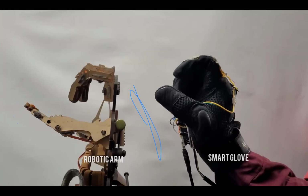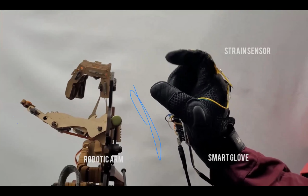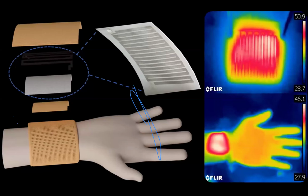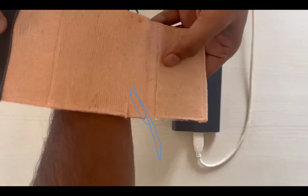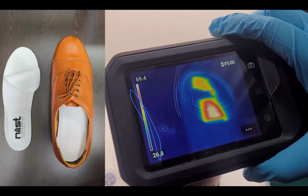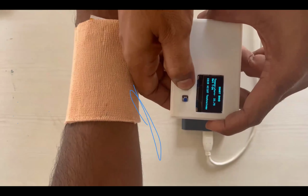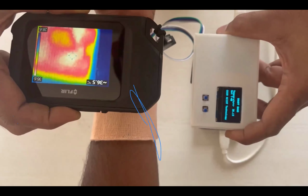The same ink is also used to develop a printed piezoresistive strain sensor, which transduces hand gestures to a robotic arm. We have also developed printed silver and carbon ink-based resistive heaters by replacing conventional coil heaters for various flexible and intelligent applications, such as smart bands, warm insoles, warm jackets, and warm gloves. These products provide flexibility, light weight, and a controlled temperature system to ensure optimal conditions for human comfort.